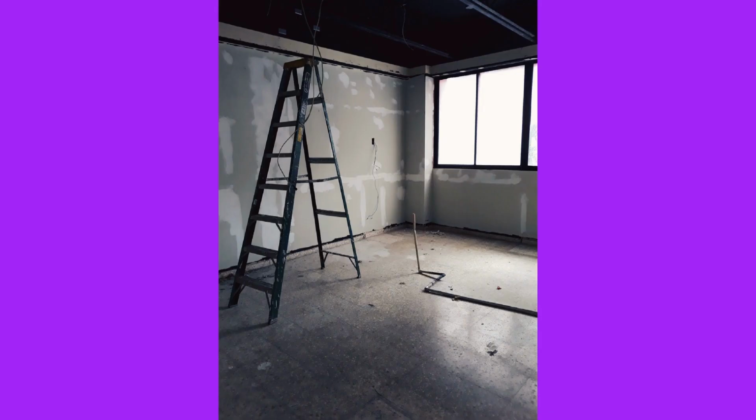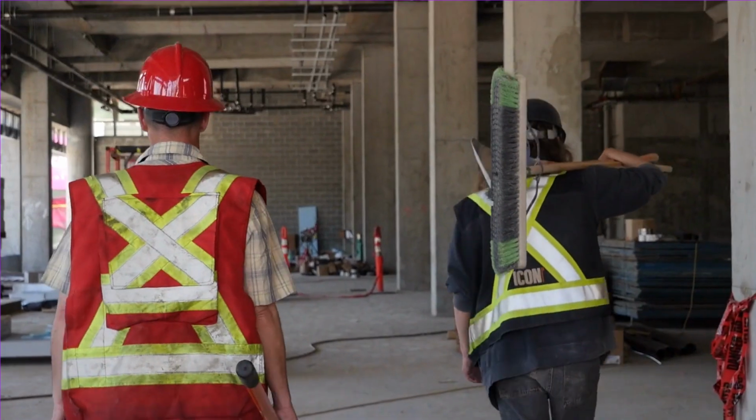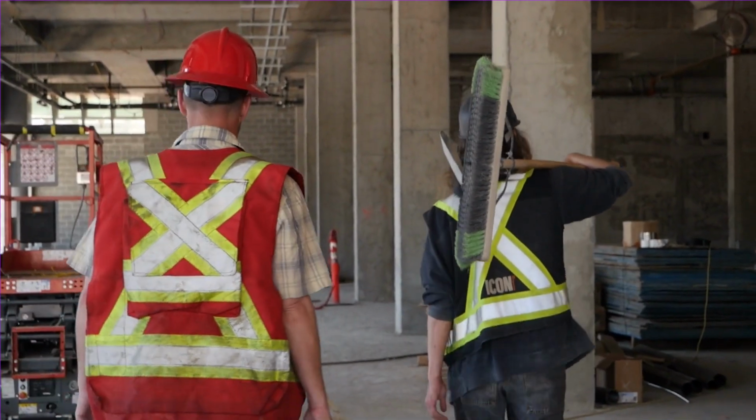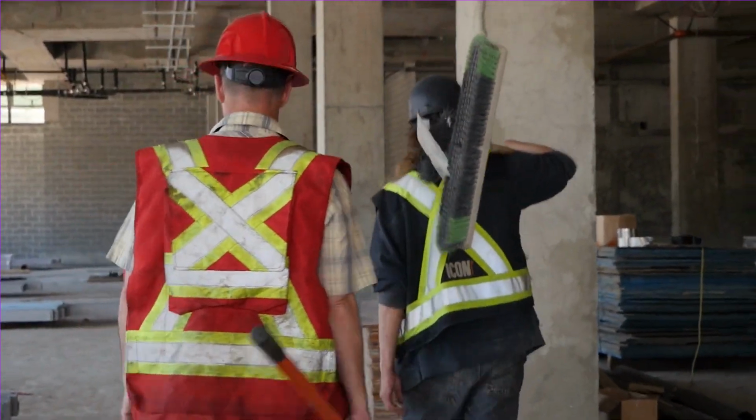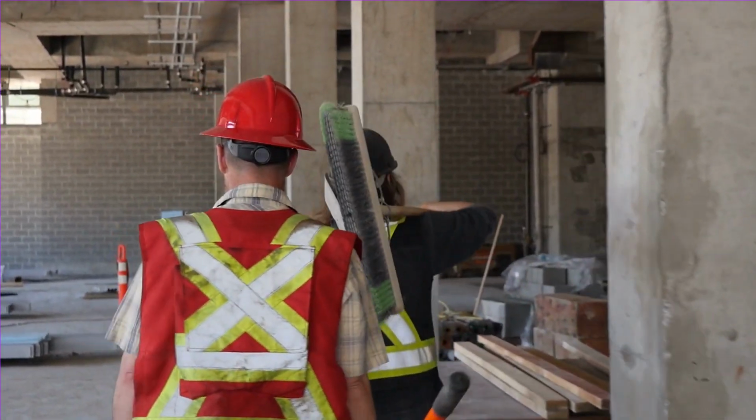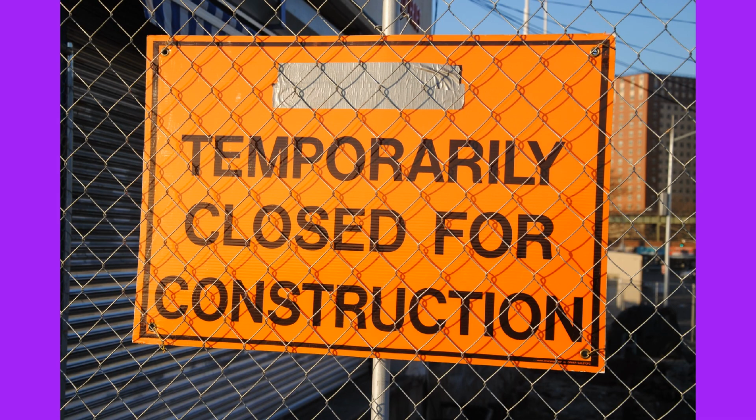Proper use of ladders. This includes using 3 points of contact when climbing, not leaning to one side while on the ladder, setting the ladder up at the proper angle, and securing the ladder, as well as other things pertaining to the use of ladders. Proper housekeeping in work areas is important in preventing falls at the same level as well as falls from height. Also, warning signs and other methods of communicating fall hazards to nearby workers are helpful.